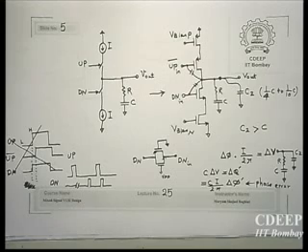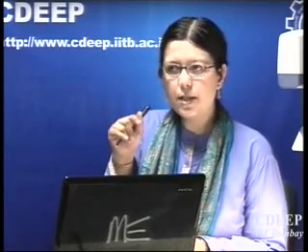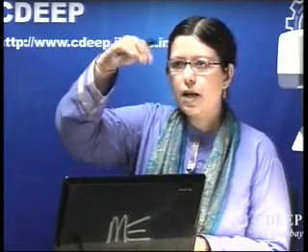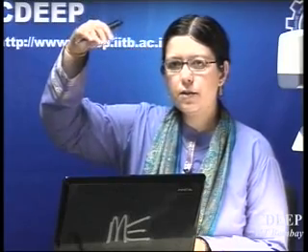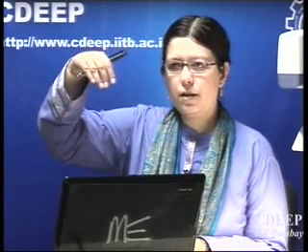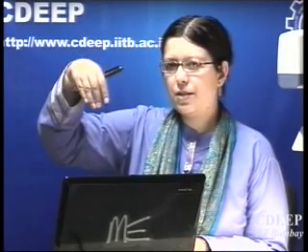Suppose the VCO was supposed to be stable at 10 megahertz, but now you see something like jitter. It will reduce and again increase, reduce, increase. The reason is that this additional error is getting accumulated as charge on the capacitor, and therefore you will get an increase at the input voltage of the VCO, and the frequency will increase.